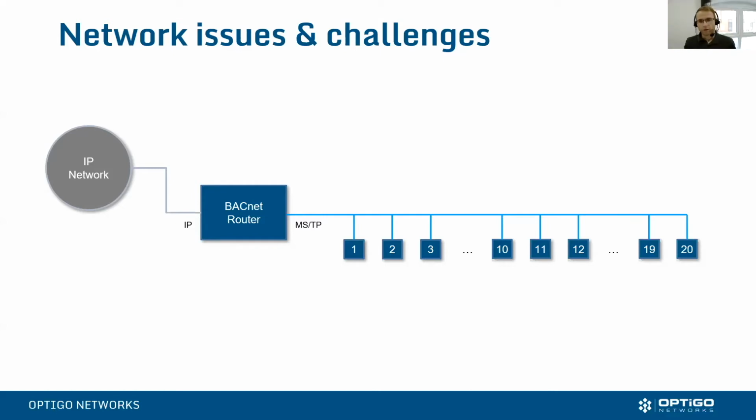So I think, like you mentioned, we were fortunate. We had Visual BACnet, a capture tool, running on this system. So we were able to take a snapshot and analyze it in near real time to see the effects we were having on the system. So we could make a small change. We could break the network. We'd drop devices off, bring them back online. Each time, run maybe just a 2-minute capture, just to see, has this made a difference or not?